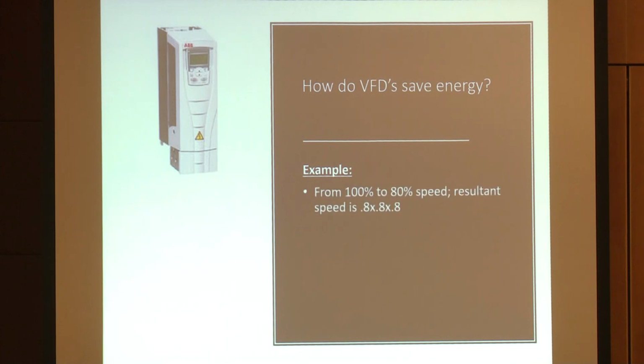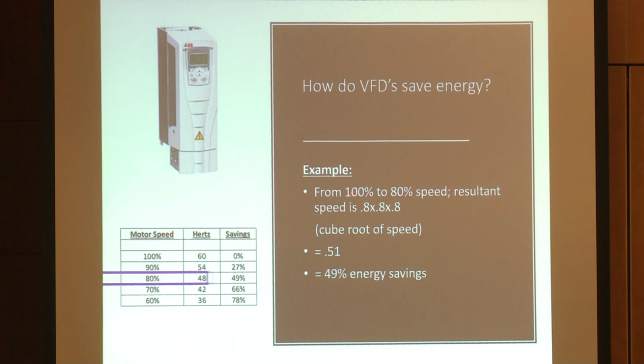Because what you're trying to do is save energy, and if you can do that by reducing 100% to 80% speed, look at the cube of the speed is 0.51. You have now saved 49% of the energy. That's fantastic. What's good for us is when we have to make an adjustment, we can simply make adjustments there instead of doing what I'm going to show you later, which is changing sheaves and changing pulleys and all this other stuff, which is very time consuming. But that's how drives actually work.